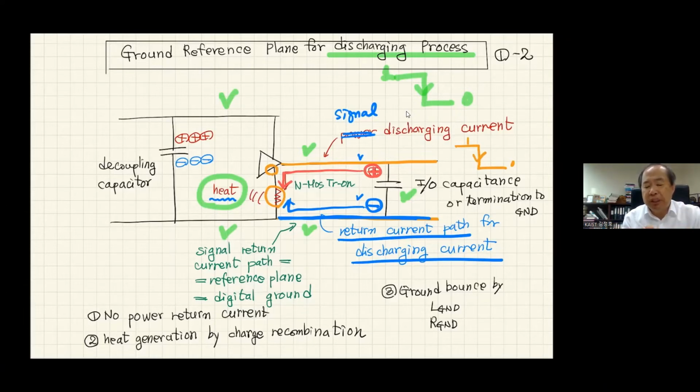And if you have 100 decoupling capacitors, you also have to secure the return current paths for each of the 100 decoupling capacitors. So this is very complicated because we're going to have 1,000 I/Os, and also the path will be different for different frequency ranges, and the return current path will be different for each charging and discharging case. By multiplying all those cases, we may have to consider 10 times cases or million times cases. That's a difficult part of the ground design.